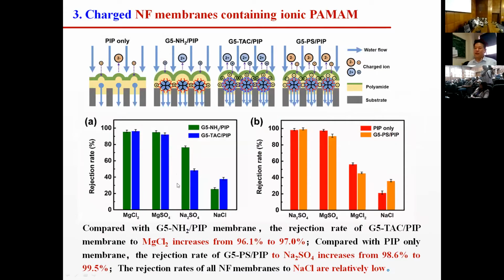From the measurement, we can find that this membrane could be charged in cationic and anionic states. For the separation selectivity, we can find from this that if the membrane is charged by the cationic state, meaning a positively charged nanofiltration membrane, the rejection rate for the higher cation salts is very high. It means the electric repulsion functions for the higher separation of